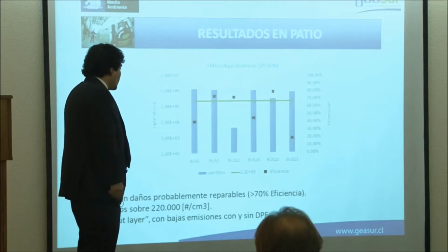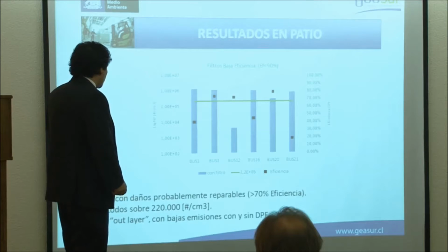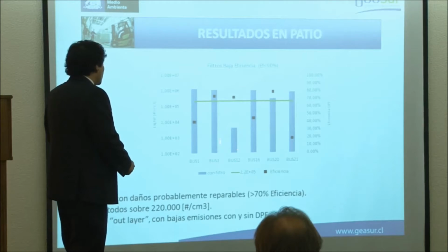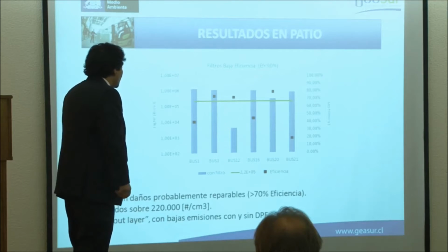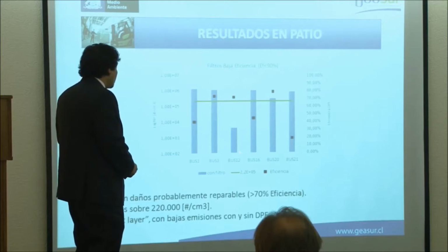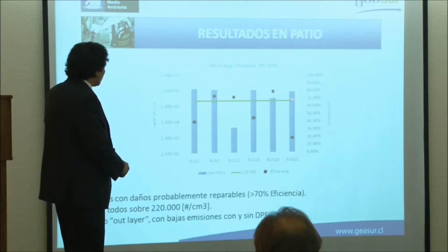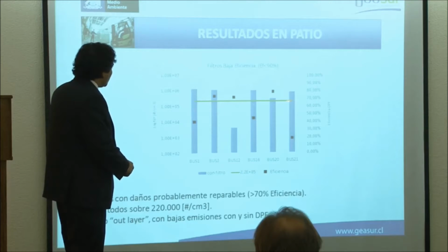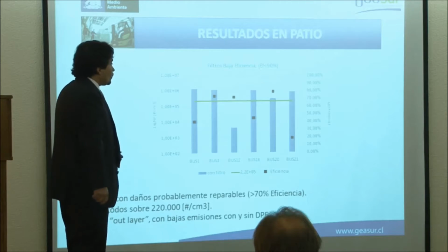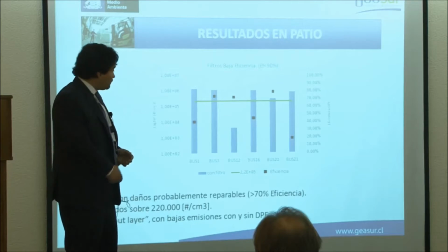There is one case which to me was an outlier, because this bus had really, really low emissions in number of particles in both conditions, before and after the filter, which is very interesting. But for all the other cases, this limit value could effectively distinguish these filters that were under 90% efficiency.